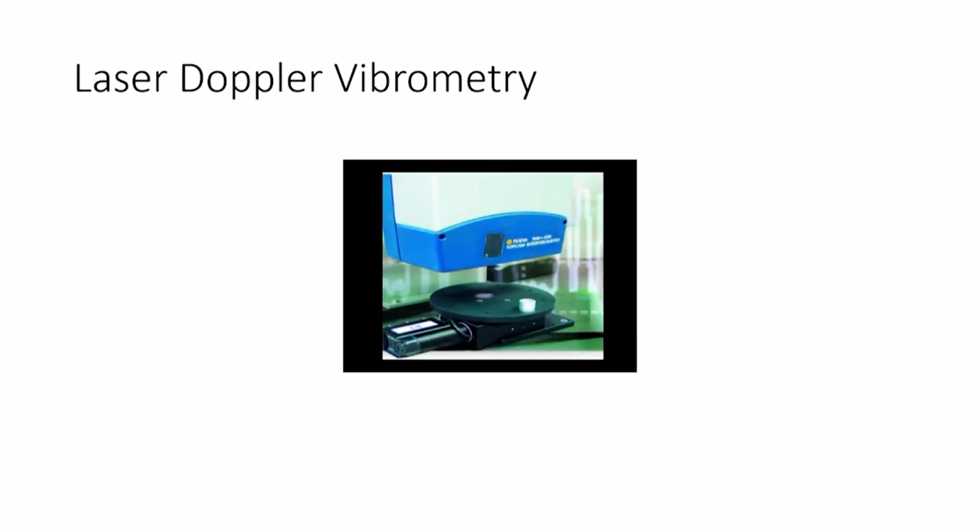Another optical technique I also want to tell you about before ending these optical type of sensors. This is known as laser Doppler vibrometry. So, what it does is that it sends a laser beam, let us say a particular laser beam is coming on an object, and the object here is actually being vibrated, okay, with the help of some shaker.